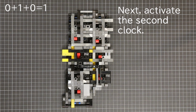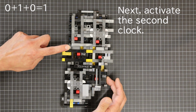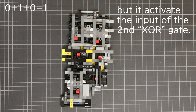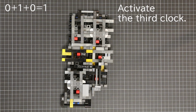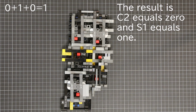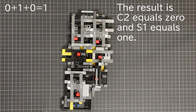Next, activate the second clock. The clock pulse is not forwarded to the output of carry 2, but it activates the input of the second XOR gate. Activate the third clock. The second XOR gate forwarded the third clock pulse. The result is C2 equals 0 and S1 equals 1.